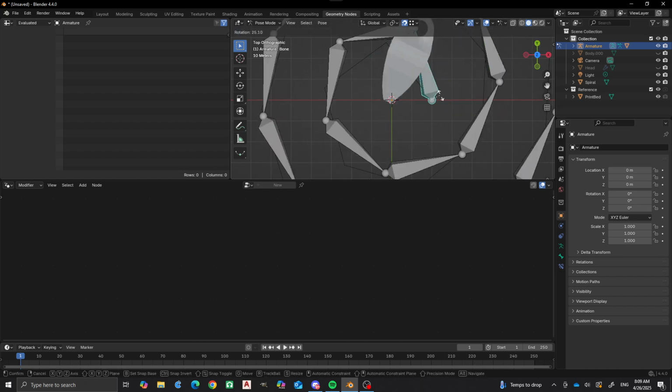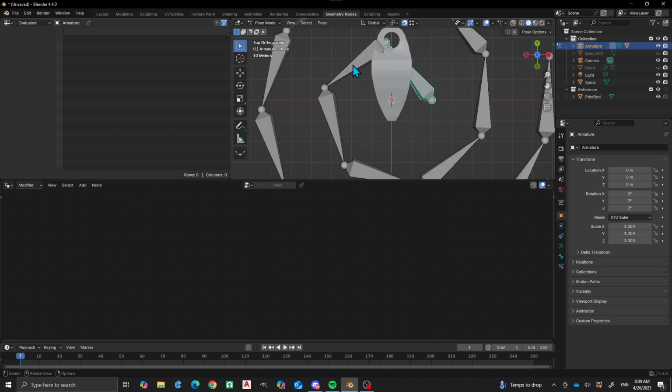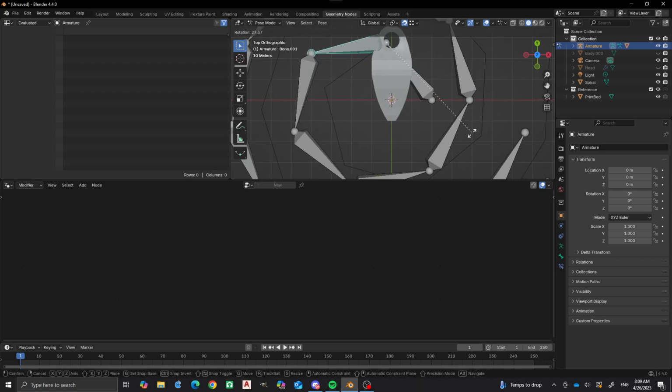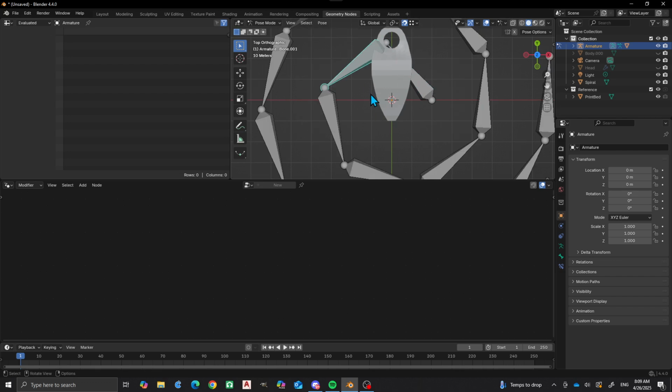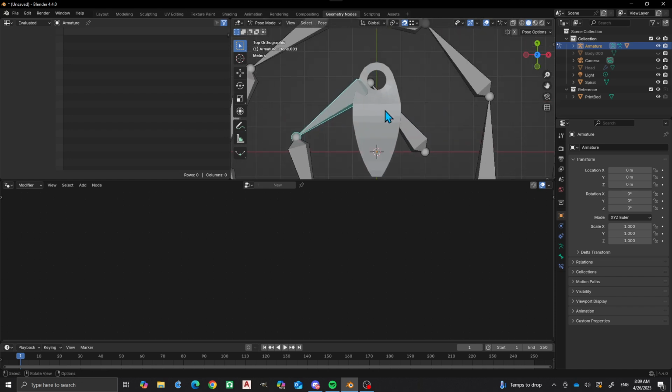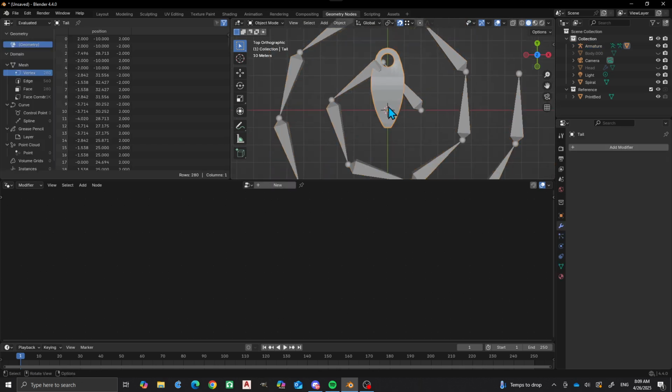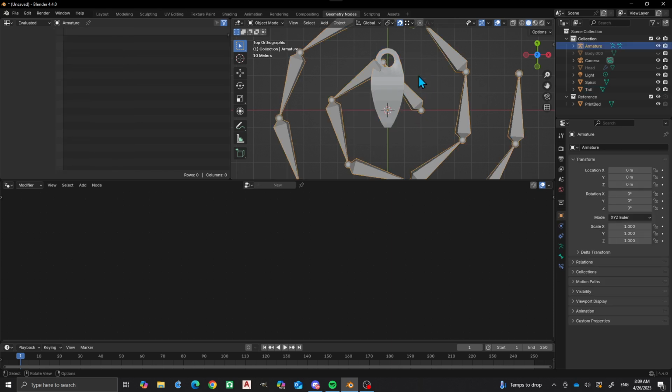You'll notice that now I have that object parented to the bone. If I were to rotate this, it doesn't move that bone or that object, right? But I also look at this, and this is not how I want to pose this. So, to fix that, I'm going to do Alt-P, clear parent. Now, to get it to do the exact location, I have to go in with Control-Tab. And then I want these two to have the same rotation. How am I going to do that?